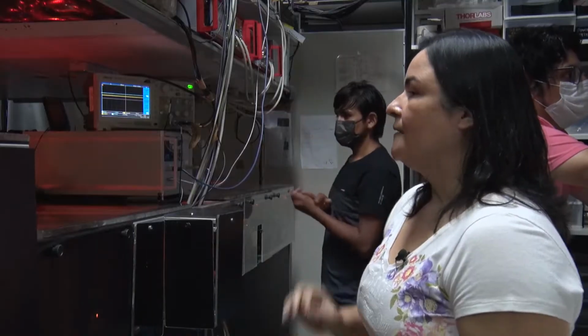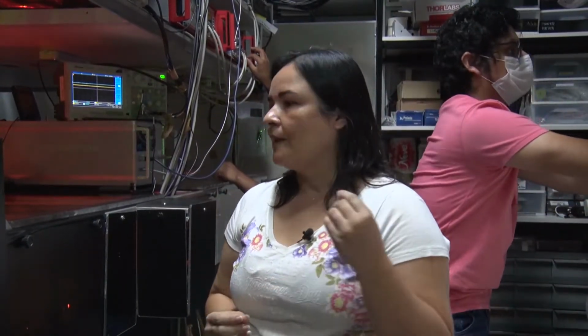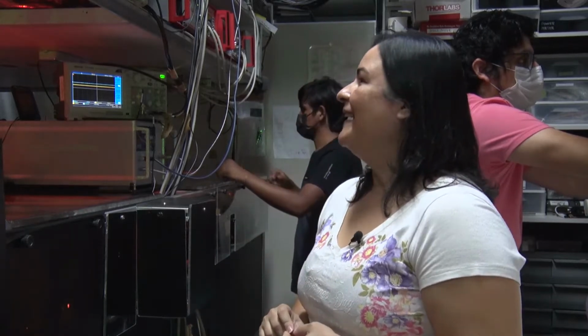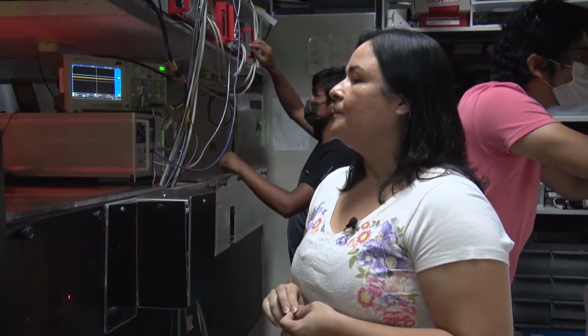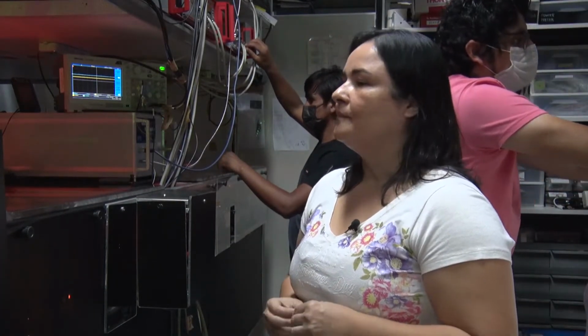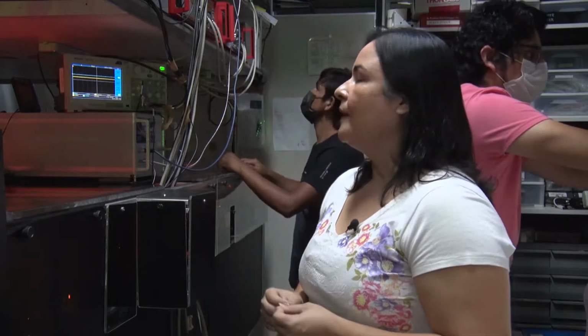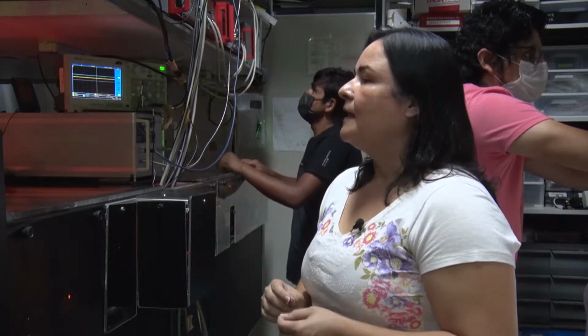Okay. But if you only have the light, okay, is enough power and so on. But also you need frequency stability, and you need a very precise stability on the frequency. Also a very precise value on these frequencies. For that, you use what you call locking the frequency using a PID system that is on this computer that I'm going to show afterwards.